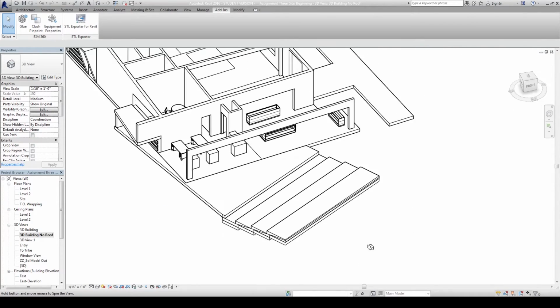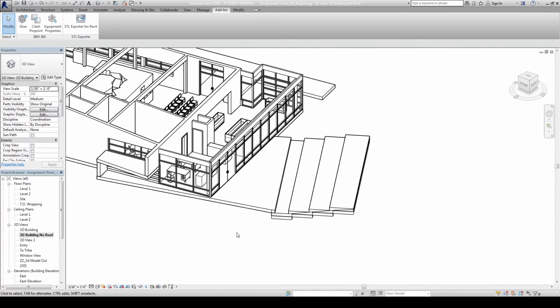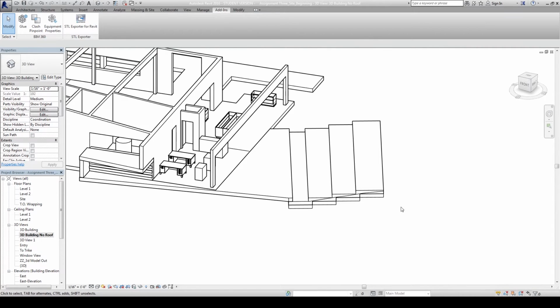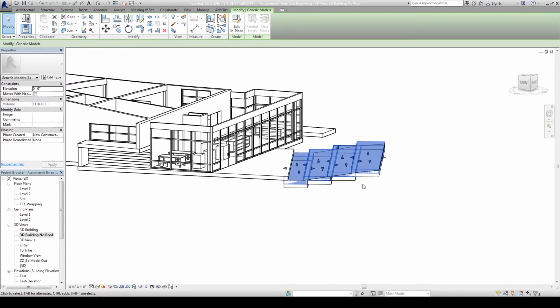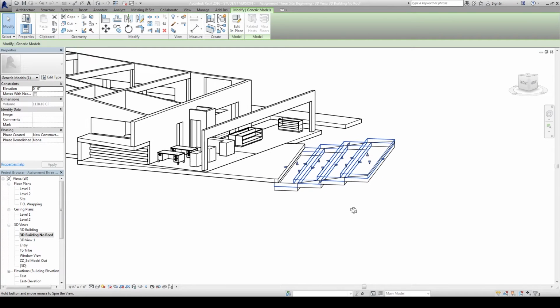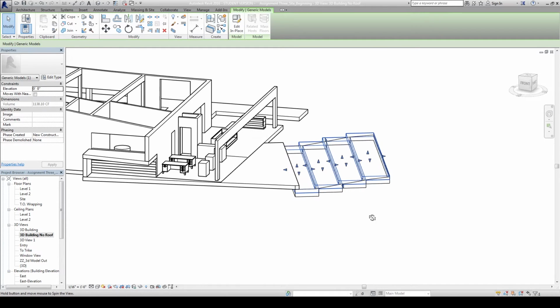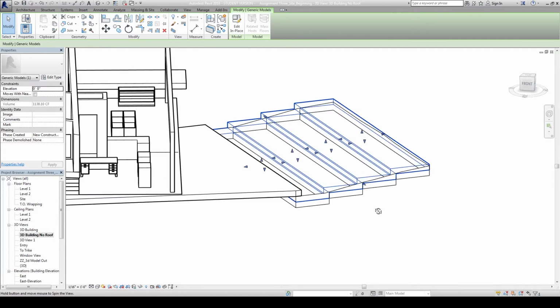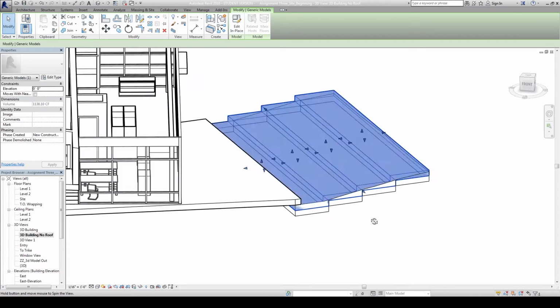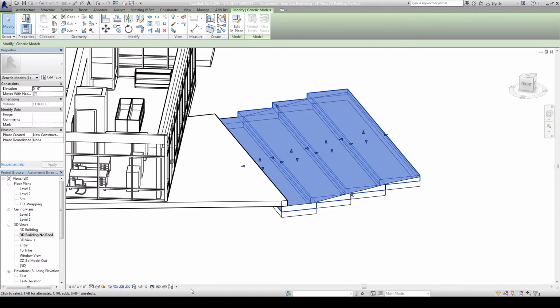I know the steps here on the back that are making up this little exterior amphitheater. Those are an element that are going to be very difficult to print, again, if we did this in situ. Because unless I built this as sort of a solid platform all the way up and designed the topography model to work with that, I would have sort of this hollow area underneath them. So again, these are another element that work very, very well to isolate, and we'll print them on edge.